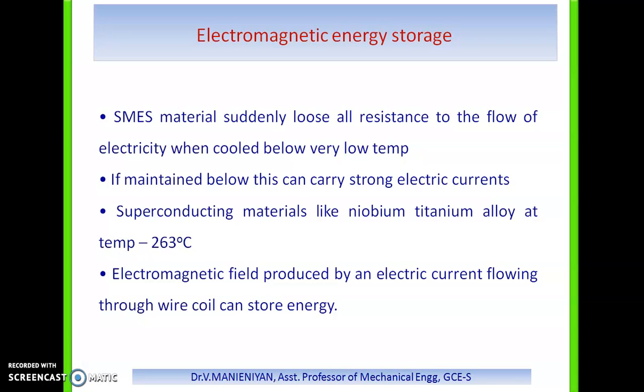A number of problems are associated with the superconducting storage system. Operation and maintenance of a cryogenic plant producing liquid helium is required for the very low temperatures. Another is that a special structure is needed to withstand the strong magnetic field. So at present, superconducting storage appears economical only at large scale, where a large insulation is required.